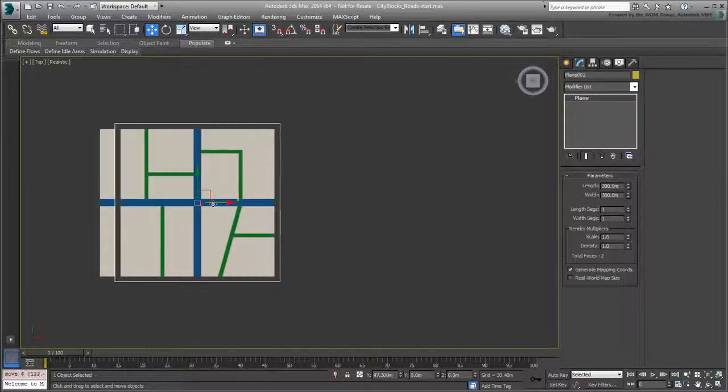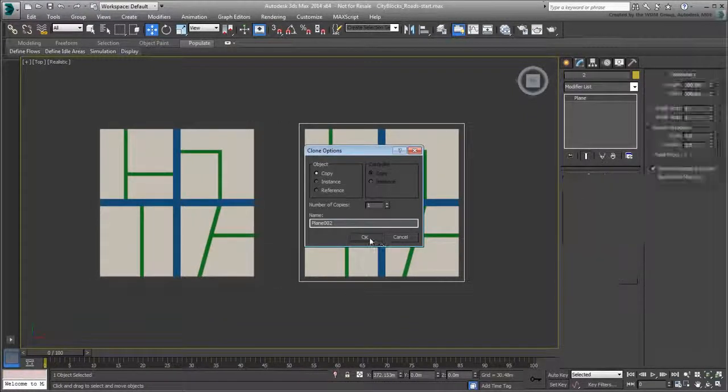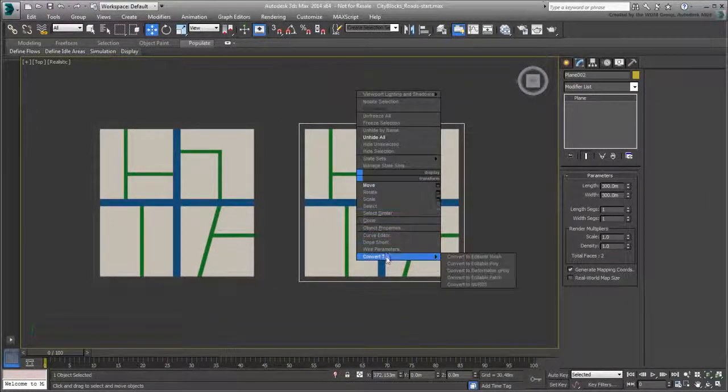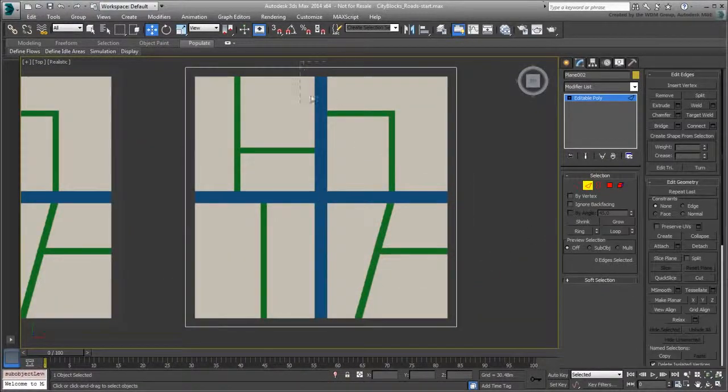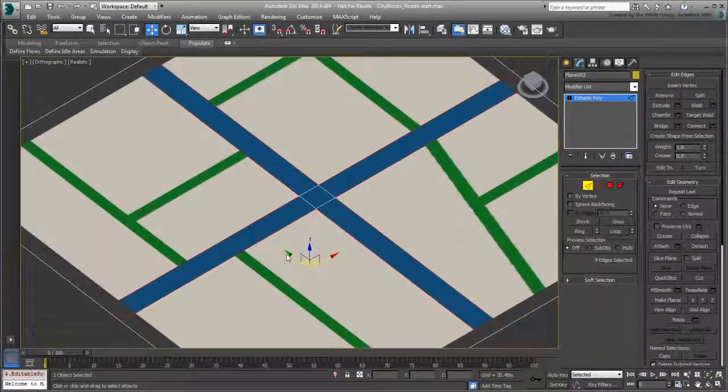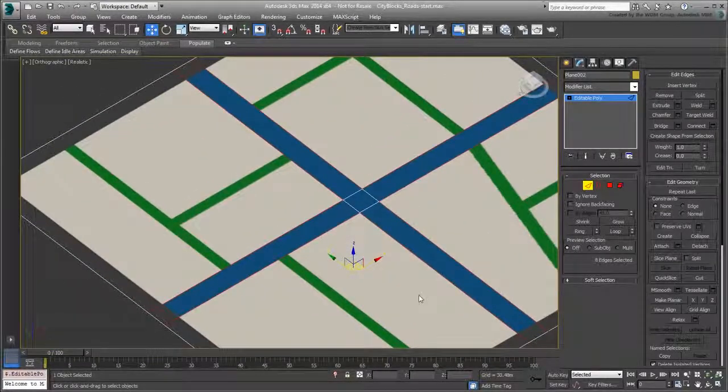If you elect to work with 3D geometry, as you have here, then one approach is to convert the object to an editable poly. You can then slice your way around the mesh using edit poly tools such as Edge Connect, chamfer, and poly insets. The difficulty in this approach is keeping the underlying texture in check. If you're not careful, moving sub-objects can distort the reference image.